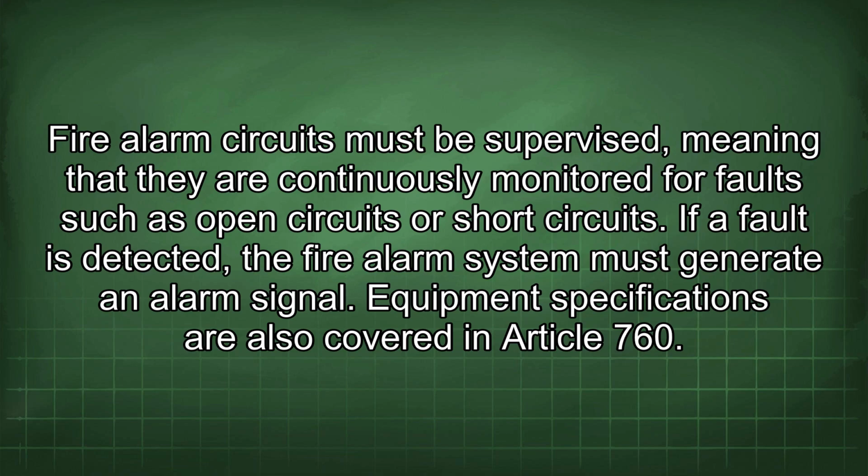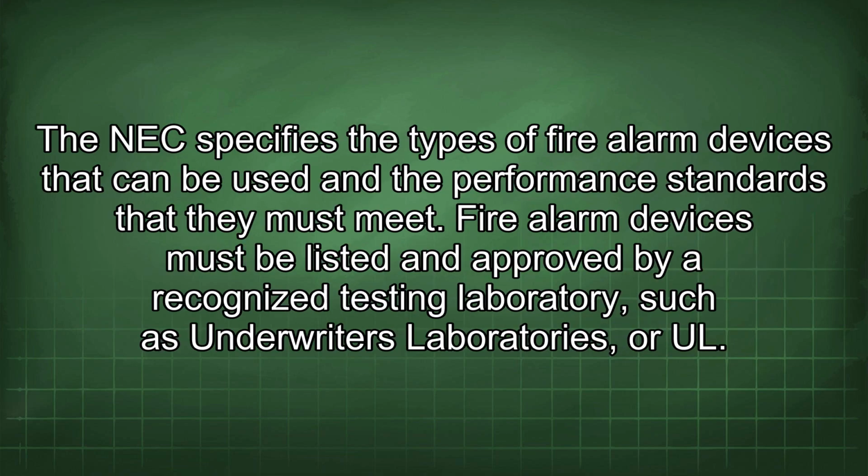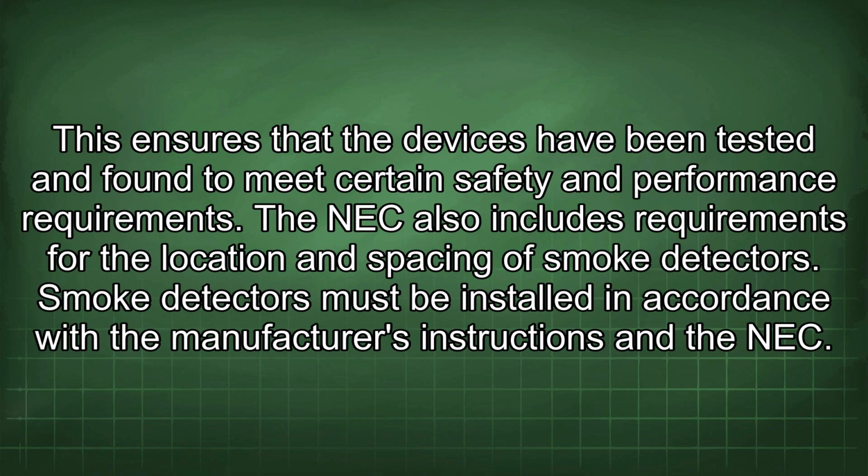Equipment specifications are also covered in Article 760. The NEC specifies the types of fire alarm devices that can be used and the performance standards that they must meet. Fire alarm devices must be listed and approved by a recognized testing laboratory, such as Underwriters Laboratories, or UL. This ensures that the devices have been tested and found to meet certain safety and performance requirements.